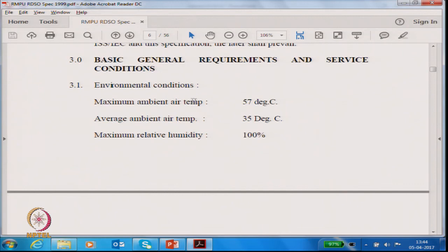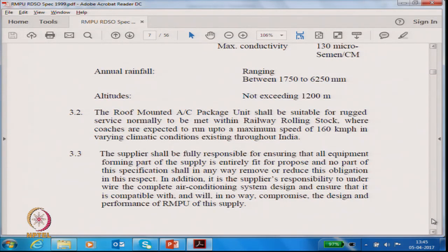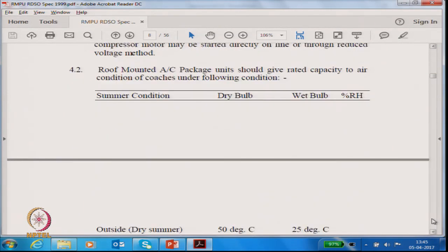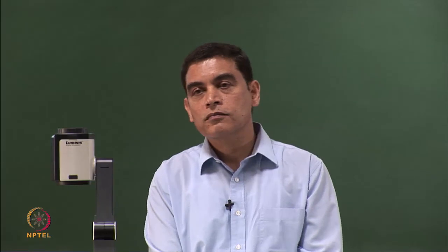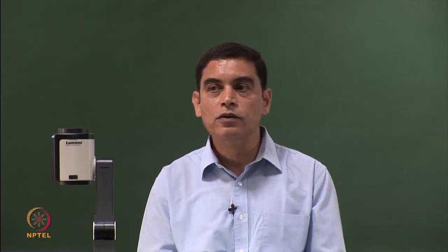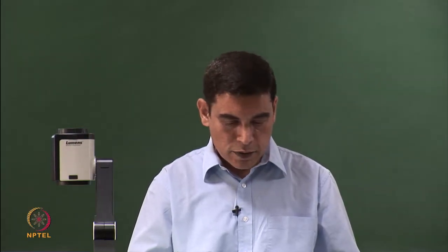Okay, so then to address the robustness part, the max ambient temperature was also increased. From 55 it was increased to 57, and the unit had to operate for 2 hours without tripping at 57 outdoor air condition. For addressing corrosion, again we had some specs introduced, and stainless steel ended up solving most of the corrosion problem. But as far as aluminium coils are concerned, they were replaced by copper. So the fins from aluminium were changed to copper, and there was an anti-corrosion coating of tin. So tin coated copper fins was one other robustness improvement element introduced in this product.